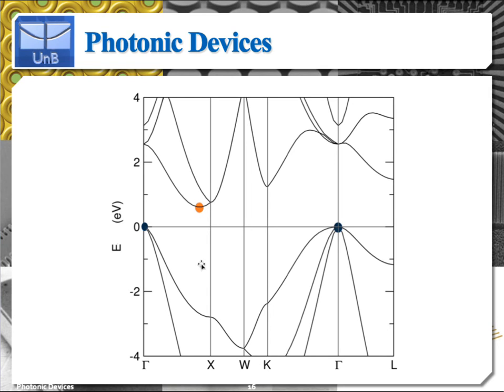But if you compare the K value of this border to either this point on the valence band or this point on the valence band, which have approximately the same energy and could be considered the borders, in either case, there's a misalignment in K between the borders of the conduction band and the valence band. So therefore, silicon with this band diagram, or a band diagram similar to this, is clearly an indirect bandgap semiconductor. Okay, the borders do not happen for the same K, as we can see clearly through these 3 points here.